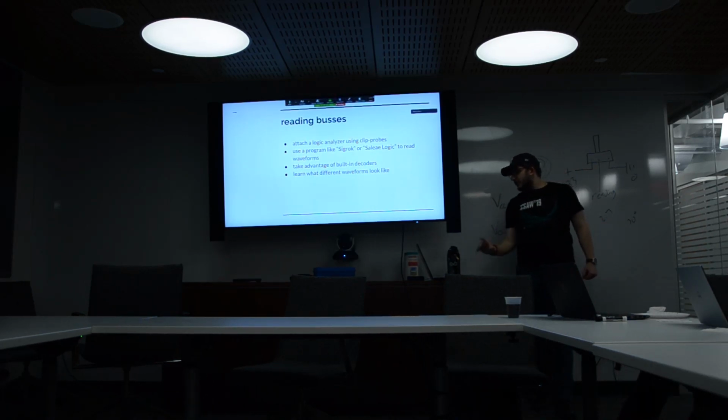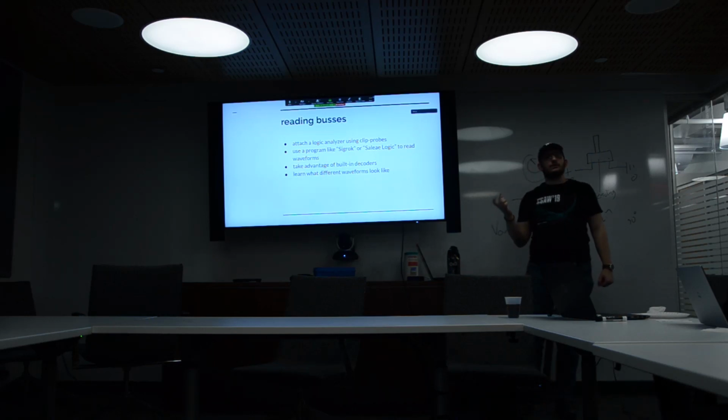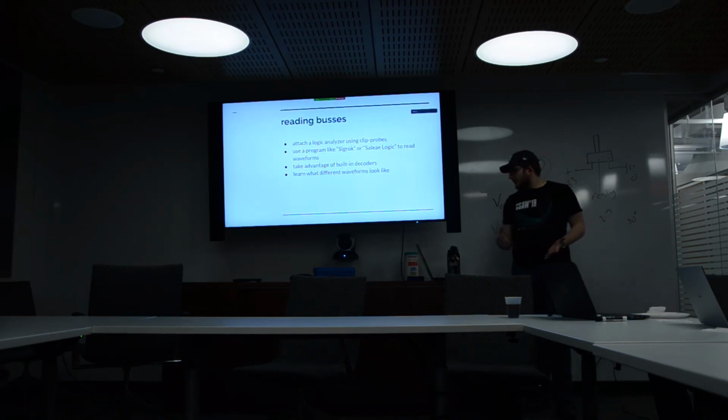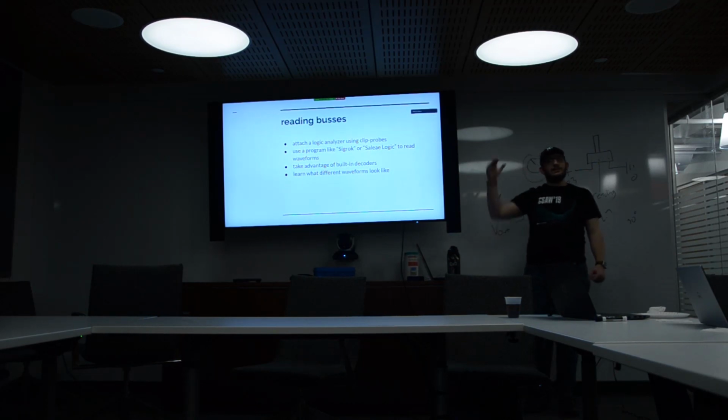These programs also have a bunch of built-in decoders on them that can natively understand UART, can natively understand SPI, can natively understand I2C, JTAG, even USB, some of them, because USB is just an electrical signal. So those built-in decoders can tell you a lot. If you successfully connect to like a UART port, for example, you say, I think I have UART on pins 2 and 3, and the decoder will try its best to get out the letters for you. And a lot of the time that actually just works.